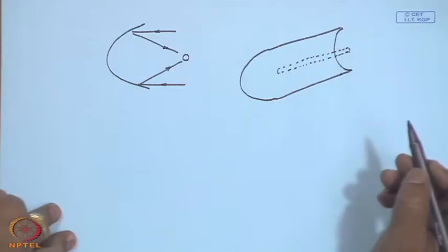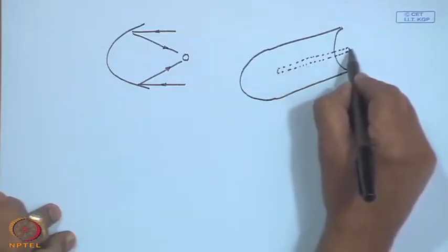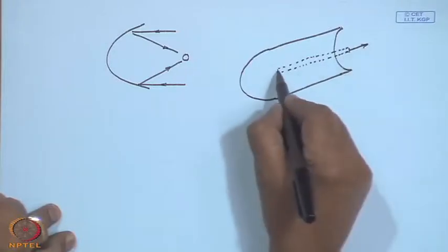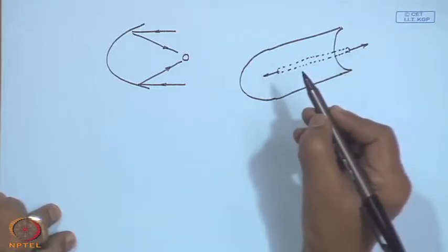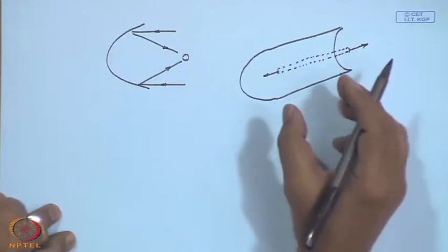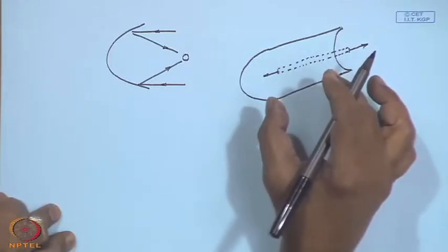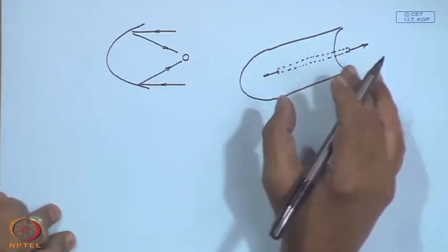So, depending upon the tracking mode, my reflected rays may go to east or west or north and south and may not exactly fall on the receiver tube. So, all that reflected radiation may not be captured by the receiver. So, effectively the concentration ratio could be different.